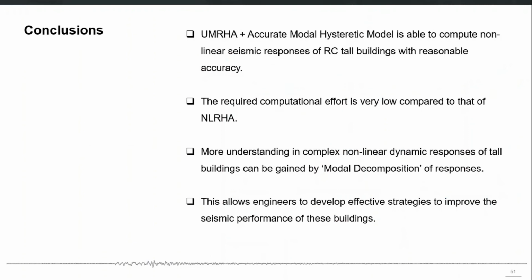So the summary is that if we can accurately develop the modal hysteretic rule or model using cyclic pushover analysis first for each mode, then the UMRHA procedure can give us an accurate estimate of the seismic response of high-rise buildings. So the computational effort obviously is significantly lower than the time history analysis, and more importantly, more than the computational time, the insight which you obtain from getting the response of each mode individually is more important in understanding the behavior of that building.